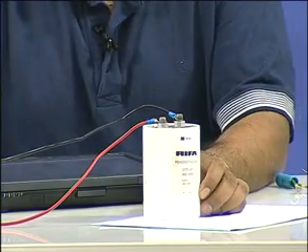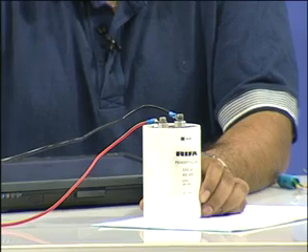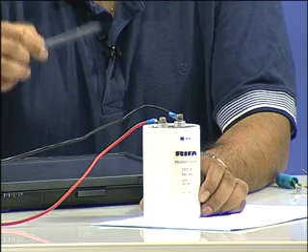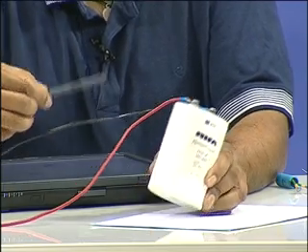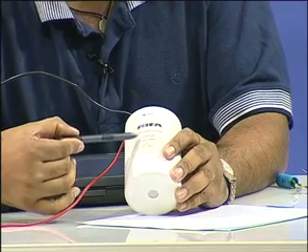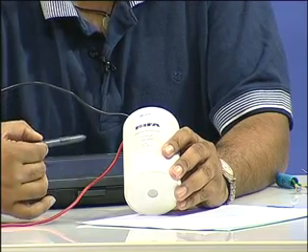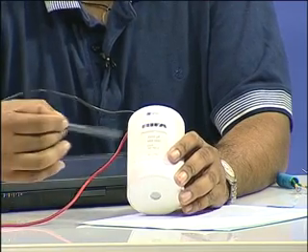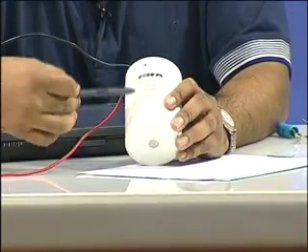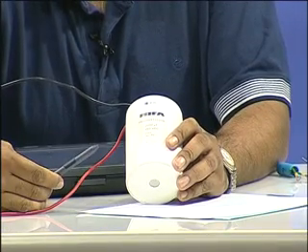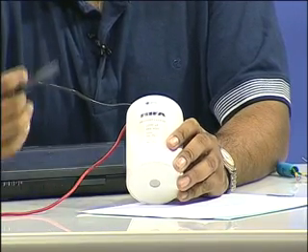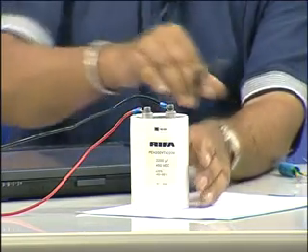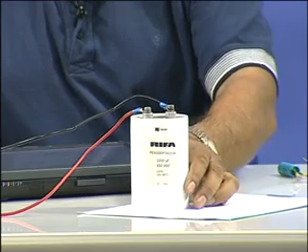values written, the two main values which we keep looking at in a capacitor, which are the capacitance value and the voltage withstanding capability. So, if you see in this, it is a 2200 microfarad capacitor and it can withstand up to 450 volts DC. Okay. And these are other numbers which you will find which indicate the tolerance values. It can go from minus 50% to plus 100%, so on and so forth. Depends upon the capacitor and the make of the capacitor and things like that.